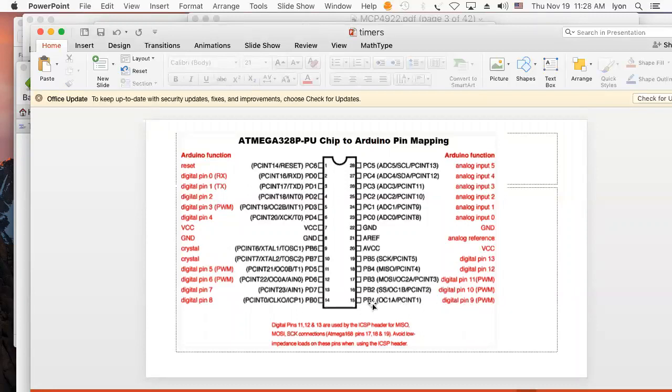Well, that's also on port B. And see how it says port B0 and port B1? That's kind of important, right? Because you're going to be writing to the B register if you're going to write these things directly instead of one pin at a time. So you can set them both to 1, 1, or you can set the least significant bits to 0, 0, or whatever you like. And that's going to essentially allow you to manipulate this port B.